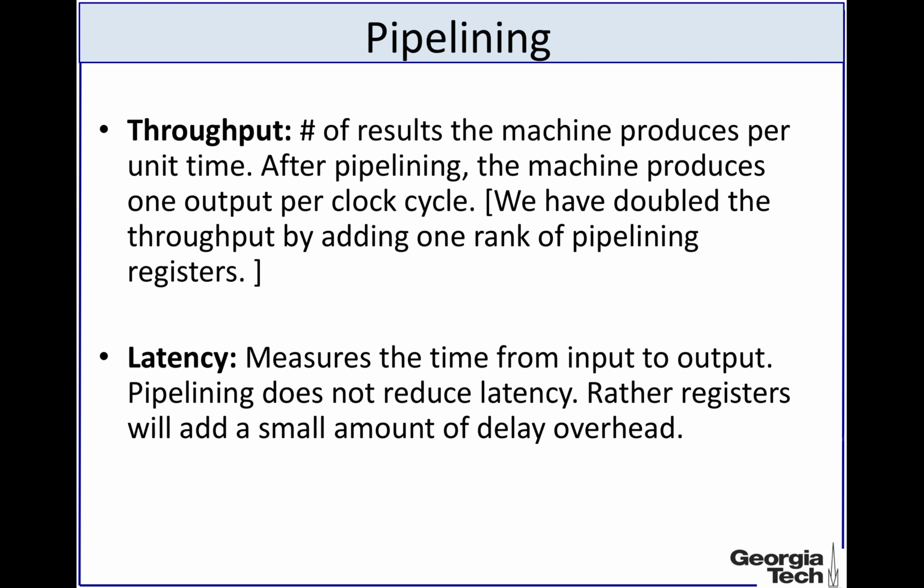But pipelining does not necessarily reduce the latency. Latency is a measure of the time it takes for an input to get converted into an output. So by pipelining, it does not mean that the latency has been reduced. Rather, the latency will actually be increased, because by putting in a memory element you have to increase the clock period to account for the setup time and the hold time of the register.